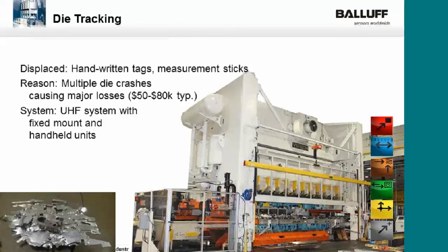We can also program into our die or into our press the setup conditions that that particular die would require, and they can all be done automatically rather than having the operator manually punch in information where mistakes can be made. So this is an area that helps reduce errors and make sure that we have the right die loaded in the press before we begin stamping parts.